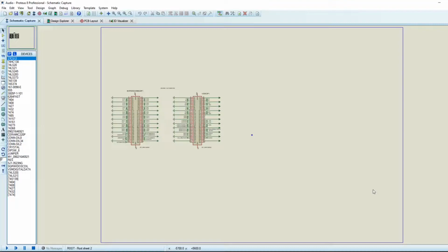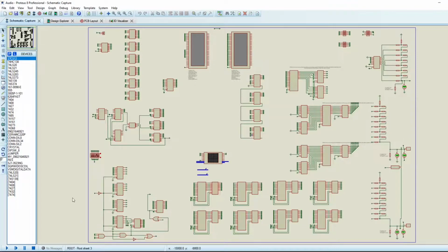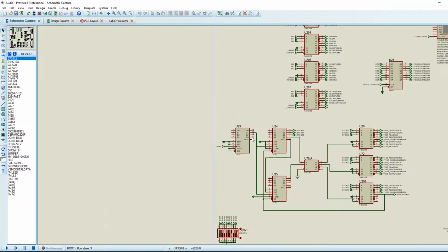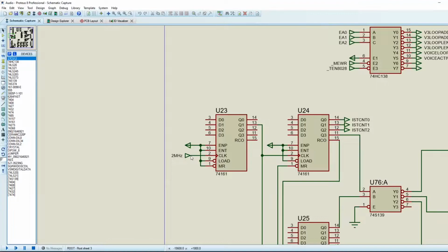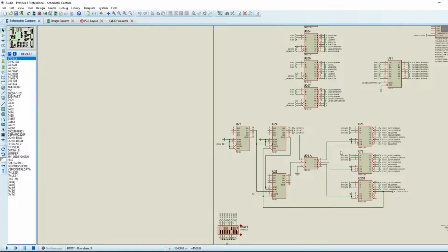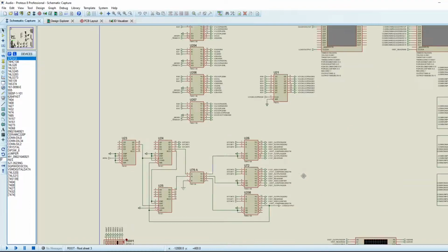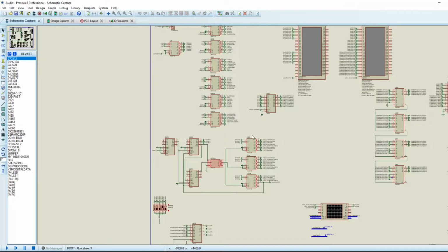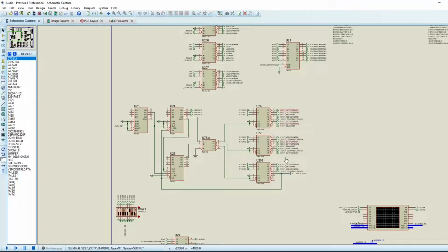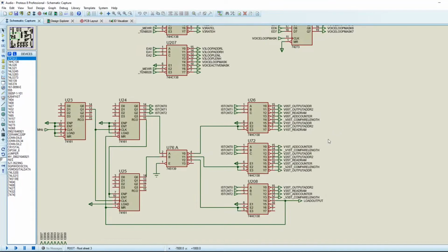This is the header sheet, so that we can actually plug the board into the backplane. And this clock signal here quite quickly gets divided down even further, so the 2 megahertz input here gets divided by 4. And then basically the audio processing hardware is a very large finite state machine. So the audio hardware has several well-defined states. We can see here, let's zoom in a little bit, that 4 voices are actually processed in sequence.